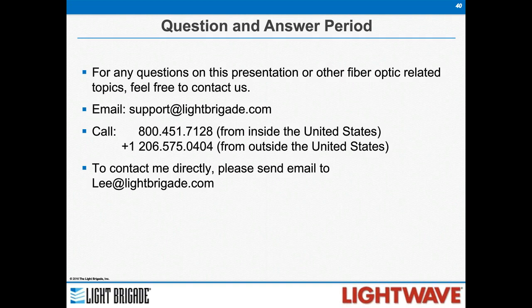Is there a standard for recommended pulse width setting for OTDR testing? Again, it really depends on the network and the length. We can provide you with some guidance, but at the end of the day, there are a lot of variables that come into play. The shorter the length, the shorter the pulse width. So if you use that general rule of thumb, you'll get some good results.